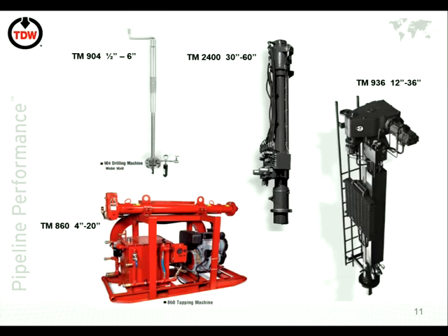Okay, which one will you use for a concrete coated pipeline? The machine itself, you can use any of them. It will depend how big it is. I mean, obviously, it will be the larger sizes. So probably this, the T2400, goes up to 60 inch, but there will be extensions of that, and we would use it. When you get up to the really big sizes, they become very special machines. They're not off-the-shelf machines.